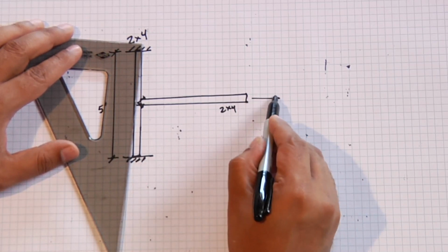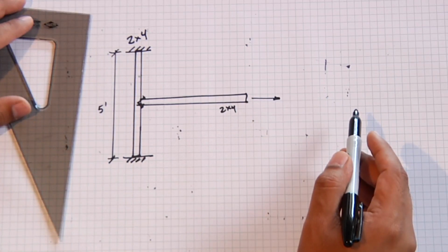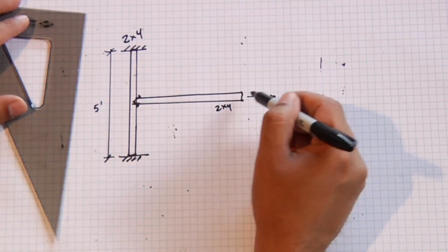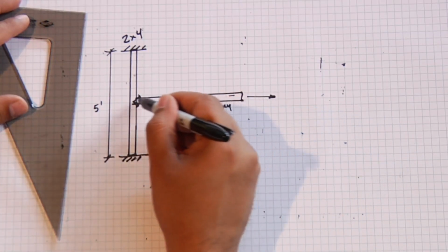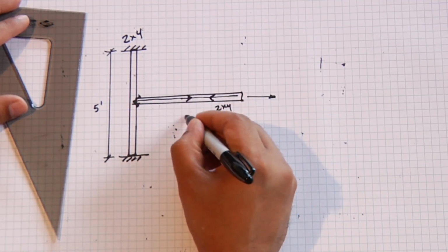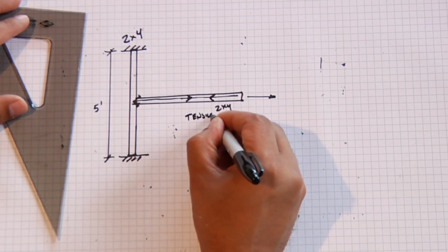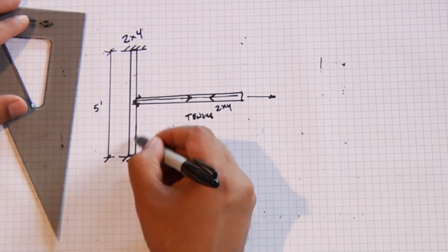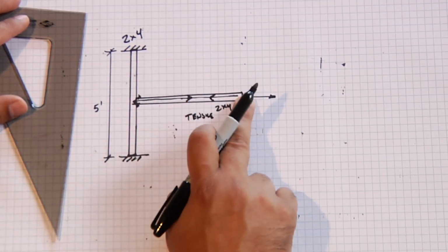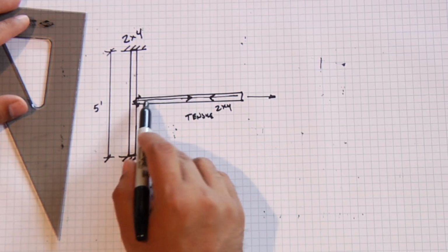And if I apply a load on this 2x4 to try to detach it from this connection, what I'm essentially doing is I'm pulling on this 2x4 in a tensile stress. This is causing a tensile stress. It is causing a bending moment in this 2x4, but if this is reasonably secure, it's going to be very, very hard to pull this 2x4 out of that connection, because you have these two nailed connections and you have this wood member coming into that other 2x4.